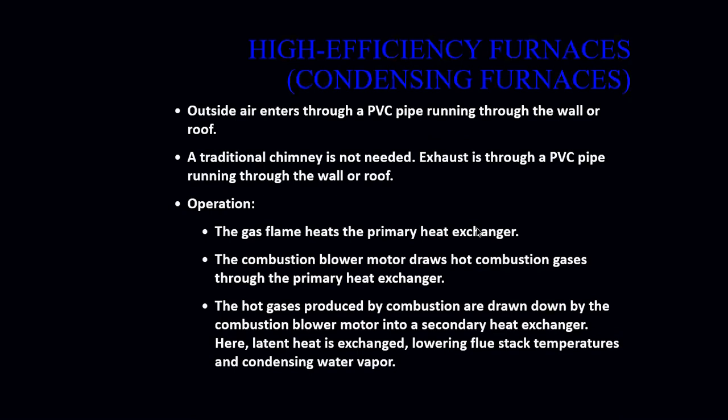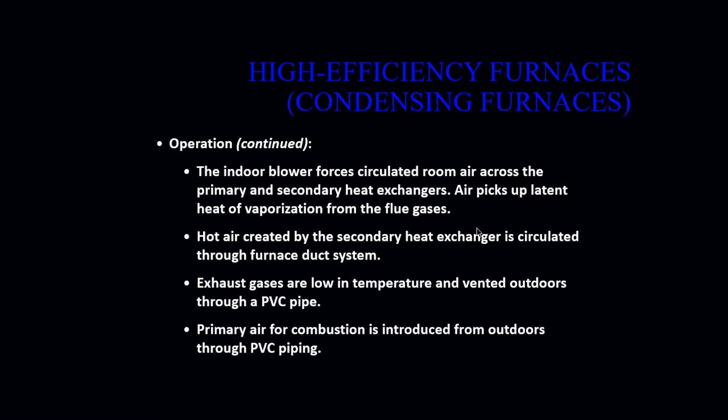The operation of these types of furnaces is that the gas flame heats the primary heat exchanger. The combustion blower draws the hot combustion gases through that primary heat exchanger. The hot gases produced by combustion are drawn down by the combustion blower motor into that secondary heat exchanger, where latent heat is now exchanged. That's going to lower the flue gas stack temperature and condense water vapor, where we are now able to send that cooler gas out into the atmosphere.